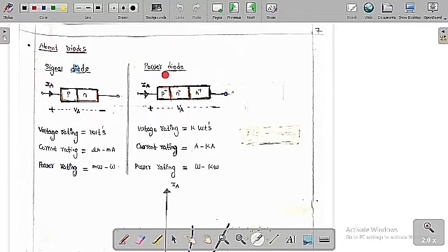Whereas the power diode. These signal diodes are used in our analog electronics courses where a small amount of rating is needed. Whereas power diodes are needed in the power system, so we need higher ratings. Because of that, we add an extra layer, an n layer, between the p and n. So we have p plus, n minus, and n plus. Plus means highly doped, minus means lightly doped. This is VA, the voltage across the anode and cathode, and this is the current IAK.